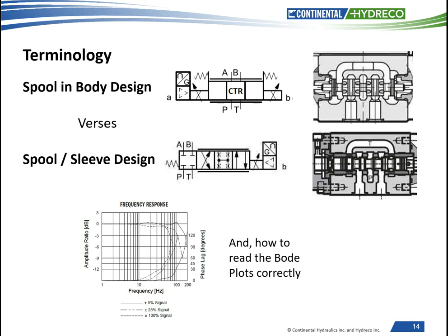Spool and sleeve designs are much higher in precision of the internal parts. The variance of the body casting and other mechanical parts are eliminated due to the sleeve. A spool and sleeve valve also uses a single solenoid for the complete movement of the spool against an offset spring. The fail-safe position is a fully spring offset condition when powered down. The powered on valve center condition means that the solenoid is basically receiving 50% amperage. So when responding to a command signal for a movement, there is no time delay, as the coil is only reacting to an increase or decrease in power.